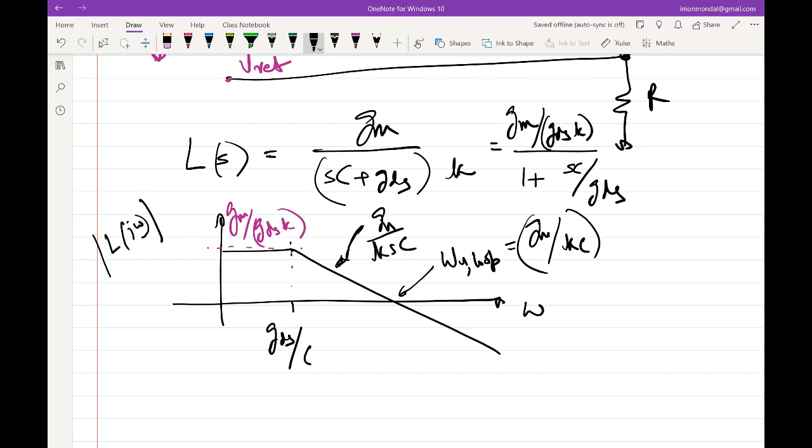That is number one. Number two is your DC gain. As we saw in the previous classes, DC gain essentially dictates the steady state error for DC inputs, right? For step inputs. Which means that there will be a difference with respect to an ideal integrator case and when you have a non-ideal integrator. And if you are particularly concerned about applications where you want to reduce the DC steady state error, then you have to ensure that this ratio of GM by GDS is high enough.